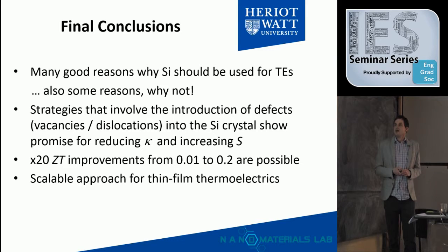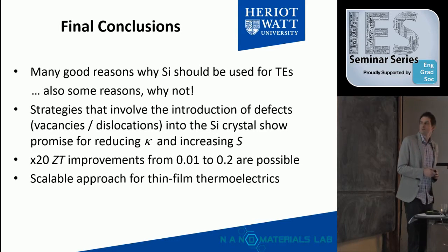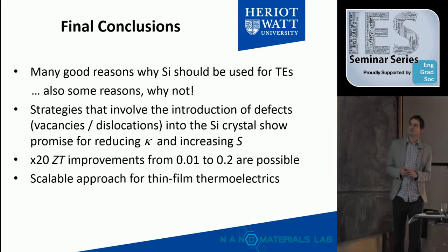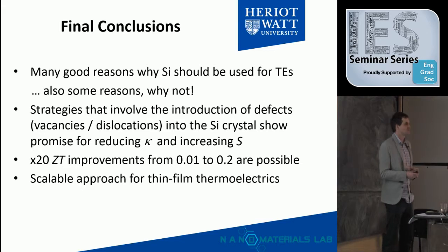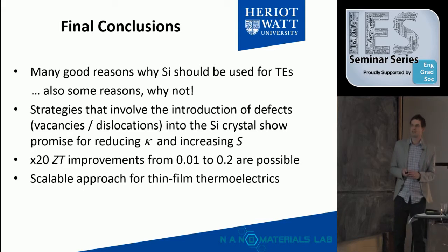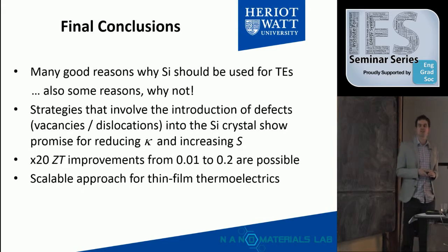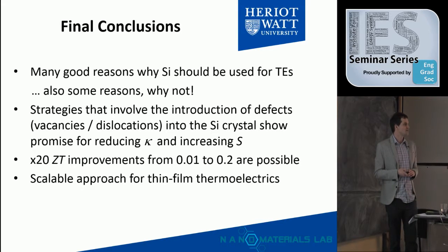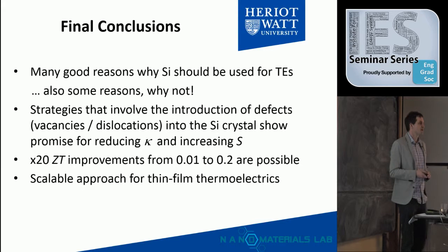So just some final conclusions. I think I'm just about on time. I think there's many good reasons why we might try to look at silicon as a material for thermoelectrics. There's also some pretty good reasons why not, and there's certainly some difficulties. We're trying to look at strategies that involve the introduction of defects to overcome some of these. And there do seem to be different strategies and different ways of improving the properties, for both thermal and Seebeck coefficient. Our best improvement so far is about a factor of 20, so getting ZT to about 0.2.